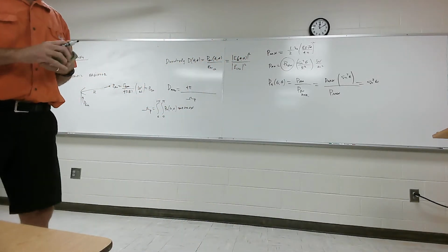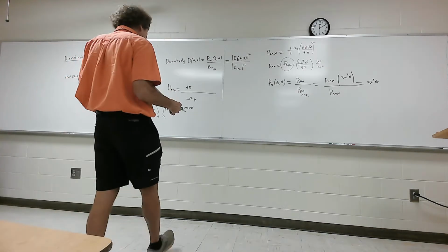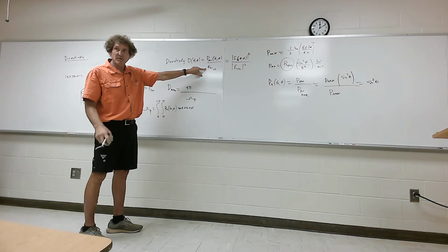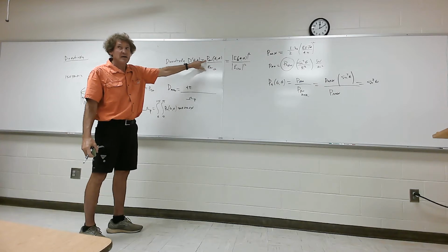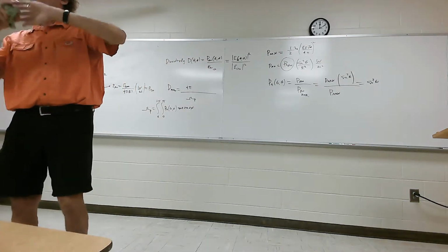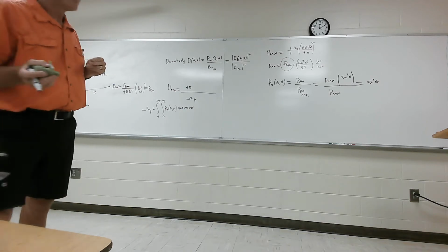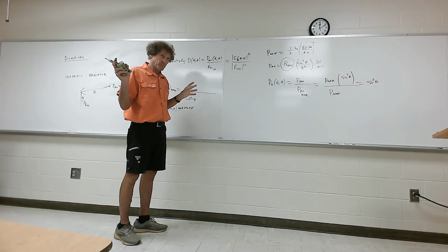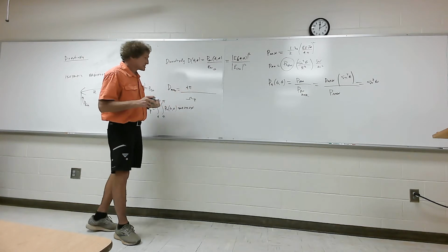Now, once we have that, I want you to bear with me in this calculation. Normally, when I do this before, what I would do is say, well, the isotropic power density is the transmitted power over 4 pi r squared. Y'all follow me on that? That would be the isotropic power density at a given range R. Then what I do here is first calculate the total power radiated by my antenna, set it equal to P transmit, and then you might say, restate this in terms of the transmitted power density. Do y'all hear me on this? When you do that, you're going to get the same exact thing as I'm showing you right here.